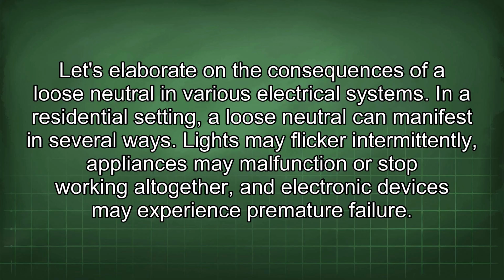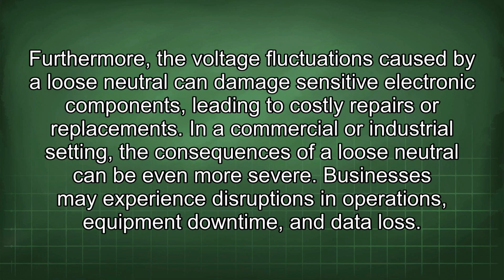In a residential setting, a loose neutral can manifest in several ways. Lights may flicker intermittently, appliances may malfunction or stop working altogether, and electronic devices may experience premature failure. Furthermore, the voltage fluctuations caused by a loose neutral can damage sensitive electronic components, leading to costly repairs or replacements.